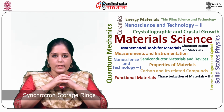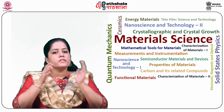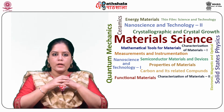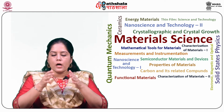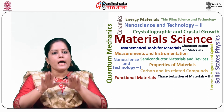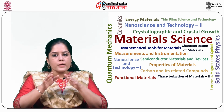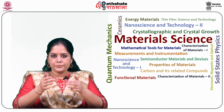Synchrotron storage rings produce X-rays of 0.1 to 10 nanometer wavelength that have been used in X-ray lithography. In the synchrotron, electrons are accelerated up to 1 giga electron volt and maintained at that energy and circulated in an evacuated ring of a pipe which is surrounded by a strong magnetic field.